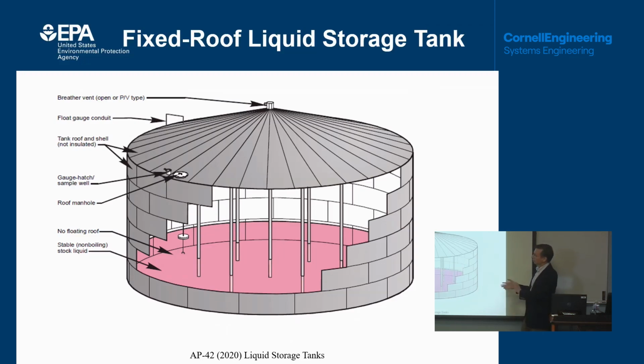So when you're storing a chemical in here, you can see the vents in there, all right? When the temperature increases in the tank, the vapor pressure increases and the amount of venting increases. If you pump something in, it also fills up more of the tank and it pushes the vapors out as well. And of course, there are little leaks as well, right? If the vapor pressure is high enough, that requires some sort of control technology. You can't just have this tank with these openings letting the chemicals out.